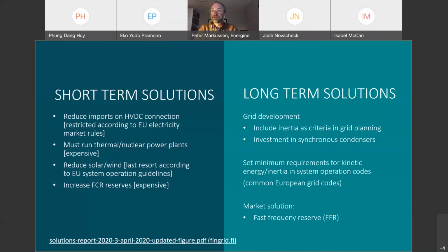But then I maybe should mention that actually there is also another thing going on. As I mentioned, the Nordic is one whole LFC block, but actually this will be changed in 2 years' time, where the Nordic will be divided into 11 LFC areas in the Nordic synchronous area, and then each area will have its own ACE. So that's also something we do to reduce the frequency deviations that we see, and then have a more robust system, less dependent on some of the inertia challenges that we see.